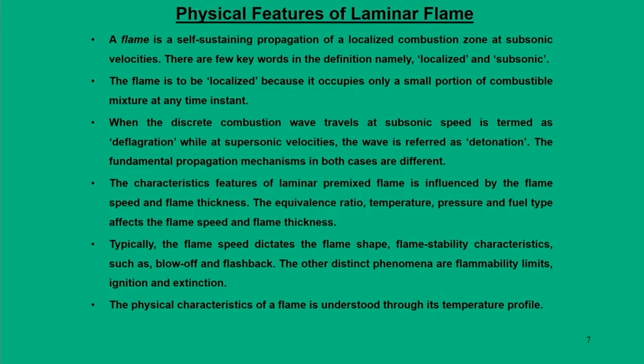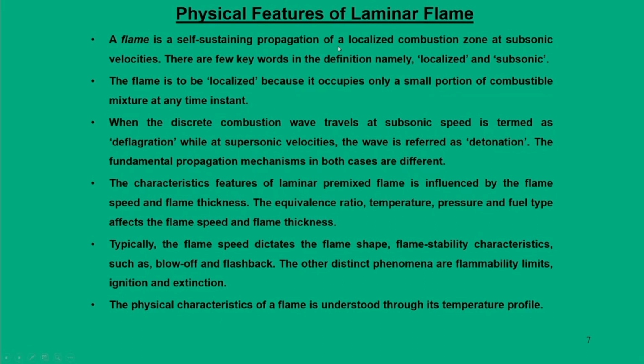So, having covered the very basic introductory part of the flame, we will now focus on laminar flame. Before you go for the laminar flame, let us understand what a laminar flame looks like, or what the basic definition of the flame is. A flame is nothing but a self-sustaining propagation of a localized combustion zone at subsonic speed. So, there are keywords like localized and subsonic. Of course, why the word subsonic?